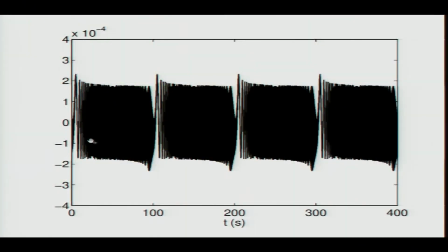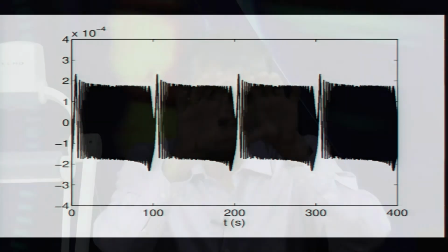If you want to avoid that, it may be better to give a multi-sine with the same frequency components, but with the phase angles of the individual sine waves chosen in such a way that we make the overall magnitude less. This is useful in case you are doing experiments while the circuit is in operation. You are disturbing it using this probing signal and trying to take out the transfer function of the circuit while the circuit is working. In that case you will inject a small probing signal, and it is important to keep it small. So this kind of probing signal is useful.